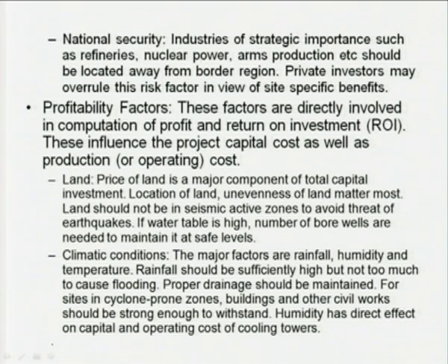Okay. The first factor is of course the land. The price of land is directly reflected in the cost of the project. Land contours or unevenness of the land would have a direct bearing on the cost of site development. Okay. Suppose you have a small culvert that is passing through the plot, then you have to go for additional expenditure to divert that particular culvert, or let us say there is a small hill on the land, then you have to demolish it and make the plot as even as possible.